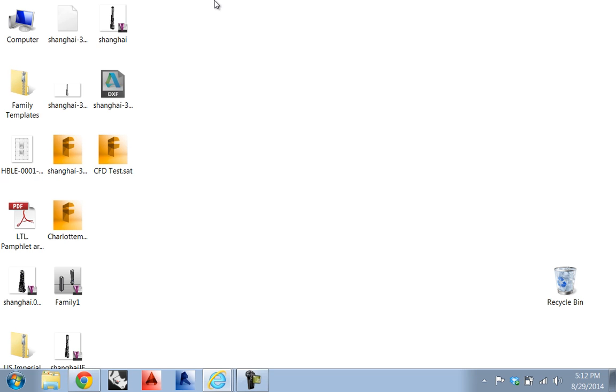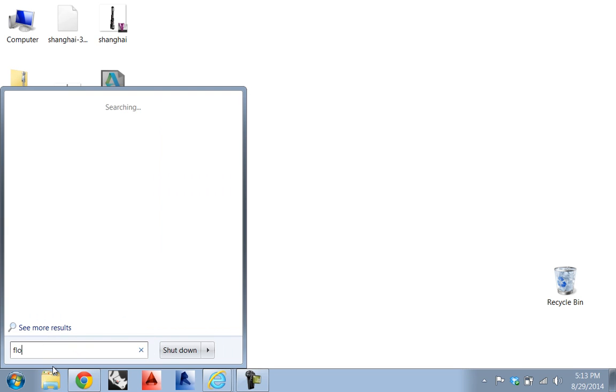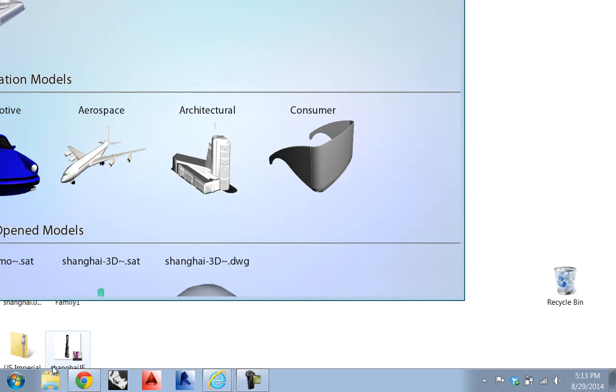Yeah, especially when you're first designing the project, all you want are the skins. You don't want to load down all the geometry because it will try and read that extra geometry, even though it's not going to be used in the model. Keep the model as clean and simple as possible at first until you start getting into, and again, we can talk about it, as we start looking at environmental systems. You may want to draw air into your building through the top of the floor slab or the bottom and set up circulations. At that point, we want to look at room level flow, and you'll probably just bring a chunk of your model in at that point.